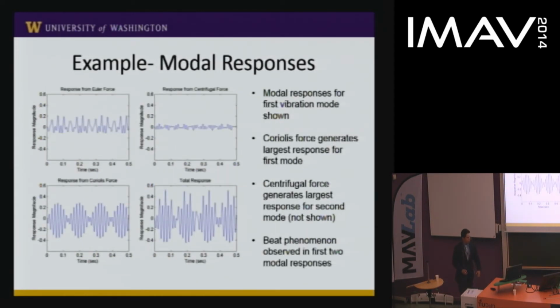So this slide will show the modal responses simply for the first mode shape. I've not shown the second mode here. You'll notice that the Coriolis force generates the largest response, and that's because we're operating near this resonance point. The centrifugal force, which is not shown, is, for the same reason, generating the largest response within the second mode shape. And interestingly, because of the proximity of the forced vibration and the free vibration, we've observed